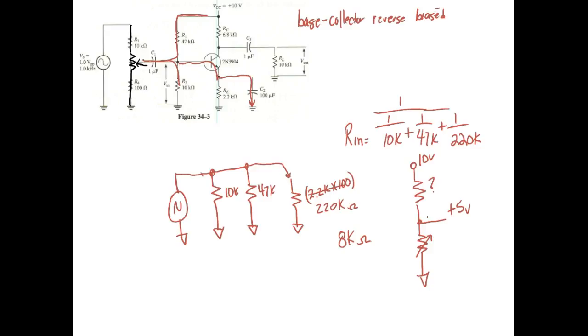Okay, but I'm talking about the ohm value. What do I know about the ohm value of those two resistors? Well, they're dropping the same voltage. They're in series. They've got the same current. If they got the same current, they're dropping the same voltage. What does that tell me about the R value of those two resistors? They're the same. They got to be the same.